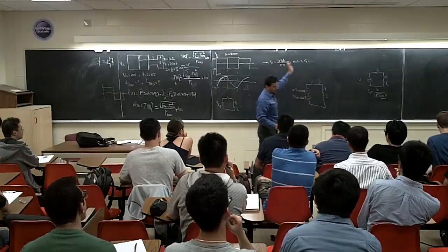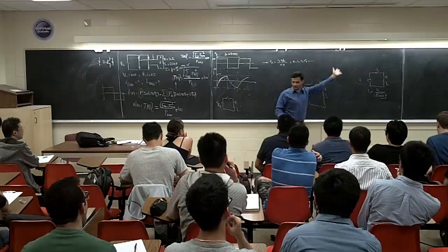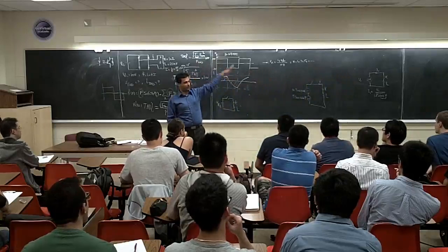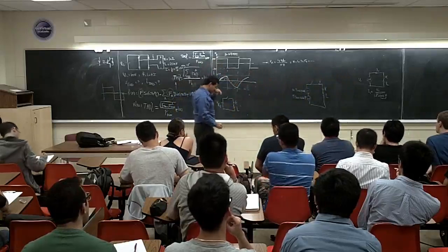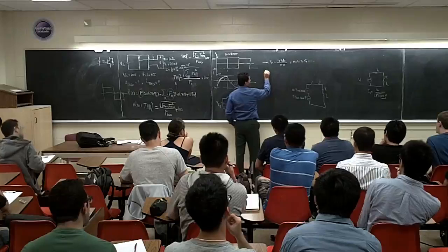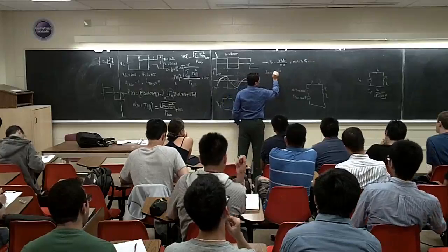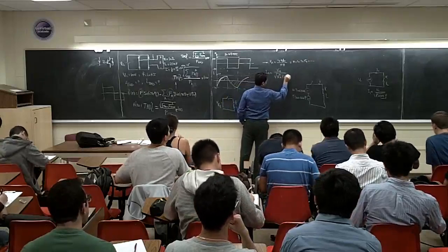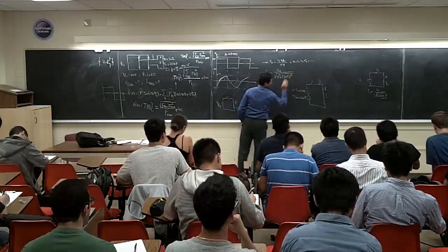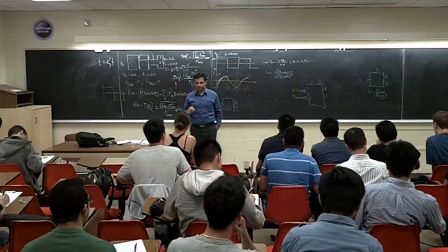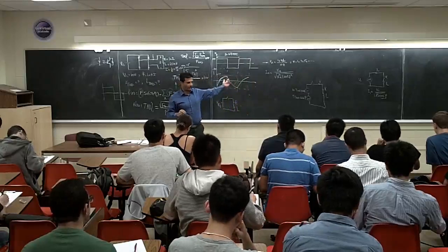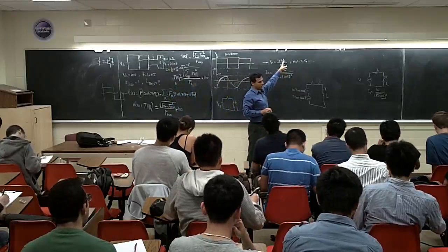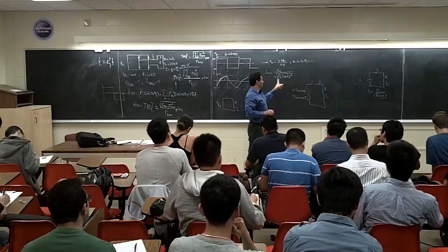Now here you have a denominator. In the circuit, it's 1, 3, 5, 7, 9, all the way. So basically In is going to be Vn over the impedance for each of them. If I want to calculate I1, n is 1, so it's going to be V1. How much is V1? 4 VDC over pi.